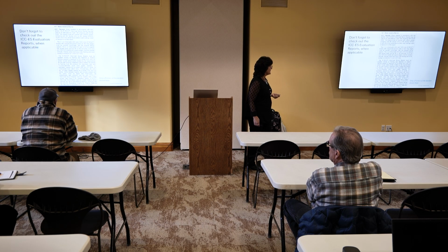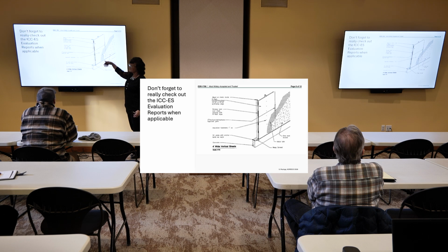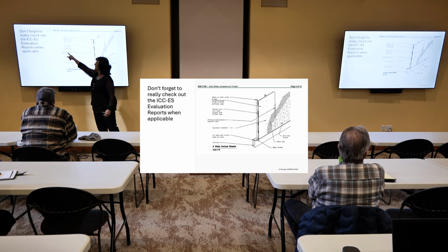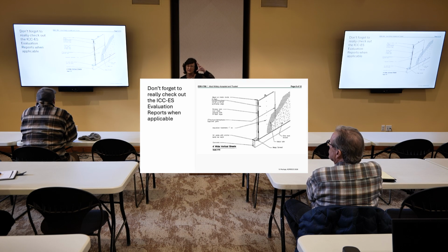So another thing it has on there are some installs. It will tell you what the screw pattern is in the field and on the edges, all of that. It'll say here, 2-inch PolyGuard 136. Well, if it says that, that is what you have to use, right? Whenever it lists a proprietary name, that's how it was tested and that's how it has to be used, unless somewhere in the fine print it says or equivalent.